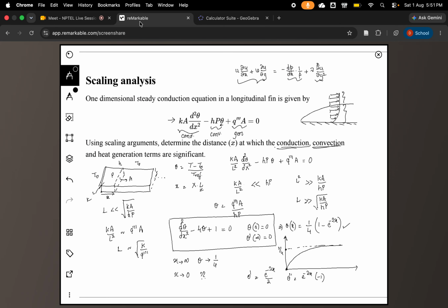So without actually solving the final equation, here to illustrate, I have shown you that we actually need a solution here. And from that solution, I tried to show you that these are happening. So what people have done is when they performed the experiments, they evaluated all these values. They measured velocity at different locations. And from there, they evaluated each of these terms. And from which they identified that there are certain regions where some terms are important and certain other regions where they are not. And from there they are able to verify the assumptions, that the scaling analysis, like you can also do the scaling analysis, from which they found out that in this region called delta, these equations are valid, and these are the boundary layer equations that are discussed in your lecture videos.